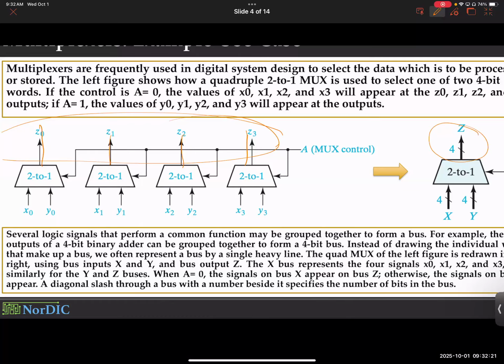And these are particularly helpful if you see, just Google it. Say architecture diagram for Core i7. You'll see different lines, like wires going in and out, and beside the wire they will write 64, 64. It represents you have 64 lines like this, each having 1 bit. So it's a bus with 64 bits. Does that make sense? So do you understand the concept of bus now? If you see a logic diagram moving forward in one of the textbooks, will you recognize that this is essentially the copy of the same circuit 64 times?